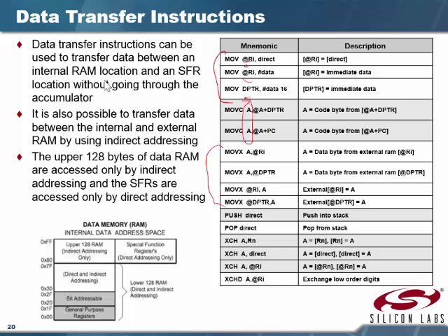The push and pop deal with the stack. Now, one of the things that you have to set up, if you're going to be using the push and pop, you have to specify where the stack is going to be in memory there, and how large it's going to be. Because if you overflow the stack, bad things happen to your code. The stack is a place of memory where you put things temporarily. You push things onto the stack, and you pop things off the stack.